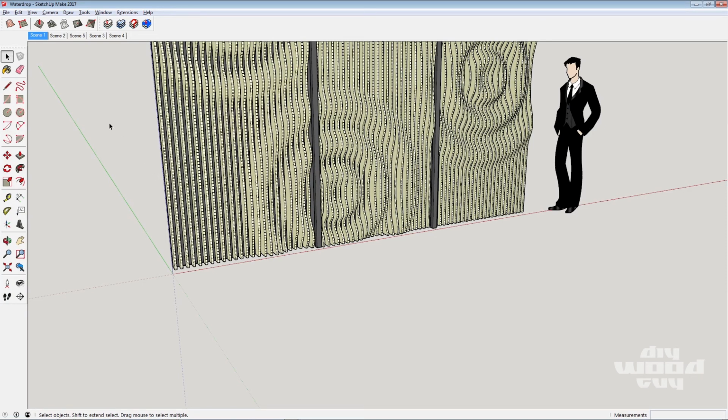Okay, our next step is going to be using Sandbox tools. We'll click on the second icon, which is the From Scratch. Now, the first time you use this icon, you're going to notice in the bottom right-hand corner of the screen that your grid spacing is 120. Before you click anything, simply type in 1, enter, to make your grid spacing at 1 inch.